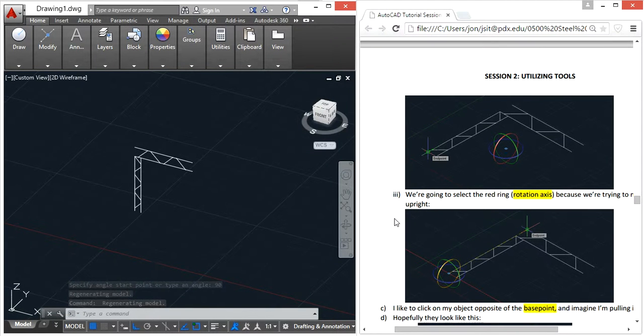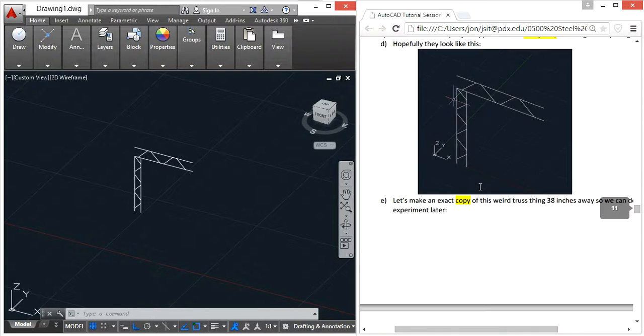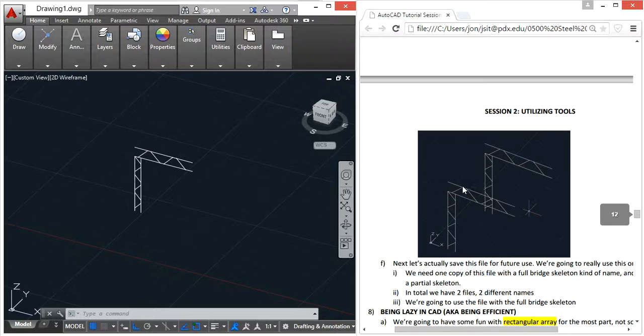It allows you to do the rotate, but whereas rotate is limited to the XY plane only, 3D rotate is specifically only this Z, this Y, and this X axis. It doesn't know how to do a special one. If you want the special one, you have to use the regular rotate tool.